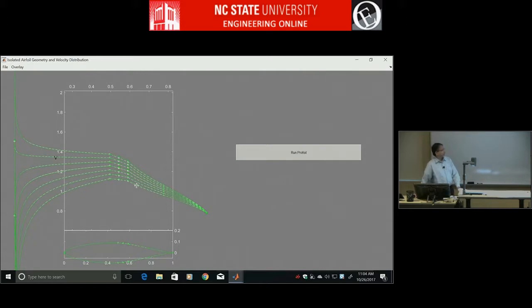In the end, you don't know how this is any better. Is this any better than the first airfoil we started with? You don't know. You have to run the two of them in Xfoil, and chances are this will be better. Other thing you can do is, the two segments that we have added, they're fairly small. You can make them bigger by enlarging this area. You can change the phi values and make them bigger. So in project 2, when you do the cambered airfoil, you'll actually be adding segments like this.